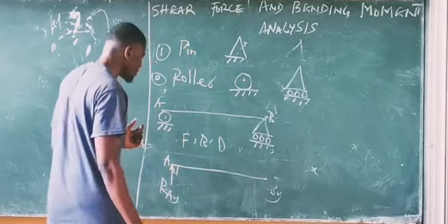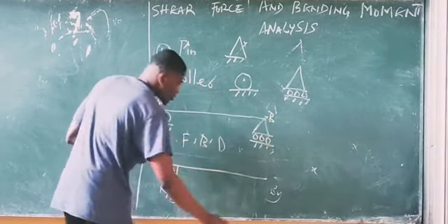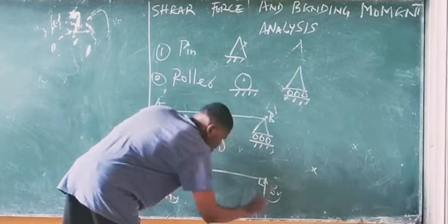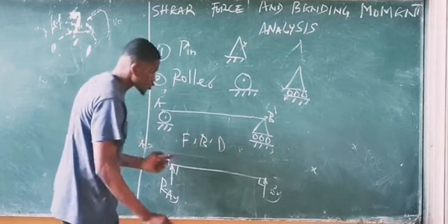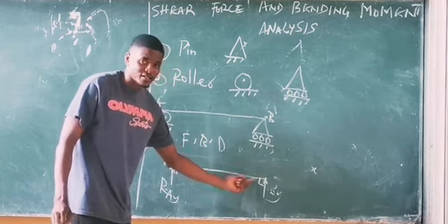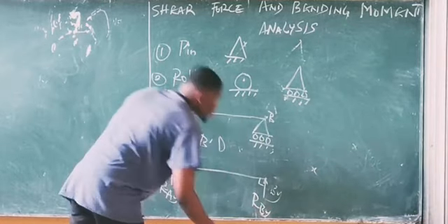Okay, we also have a reaction at point B, which is also a roller. So as well, we have our roller, one reaction at 90 degrees to the surface. So it must always make an angle of 90 degrees to the surface where the roller is acting. In this case, it's also vertical, so we have RBY.